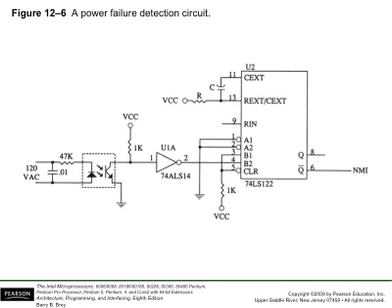Once that happens, in our case, we would like the microprocessor to go to the interrupt service routine of this NMI, and ideally, because we still have 75 milliseconds of power, hopefully during that time the microprocessor can save most of the work.